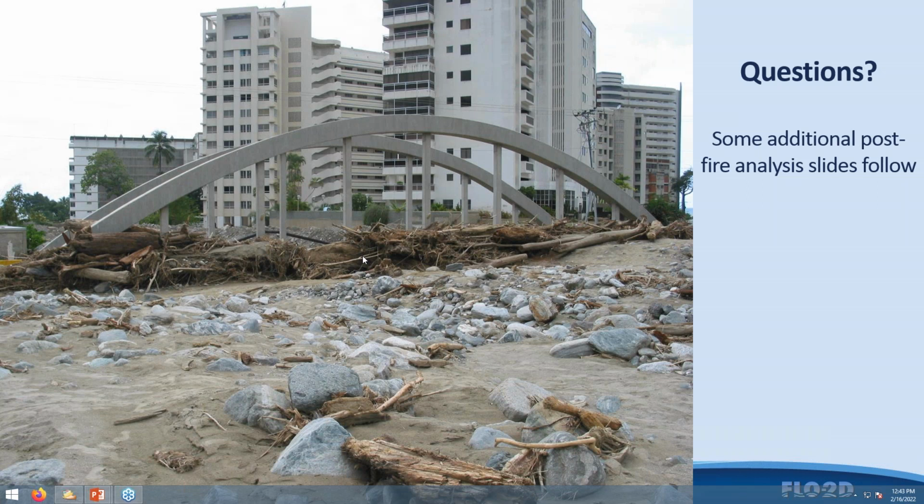But the first thing you want to do is make the average concentration by volume match that of a mudflow event, and to see if that mudflow event could occur in your basin by having the sediment supply roughly match the predicted volume in the mudflow event. And I think that's the last of our questions today.